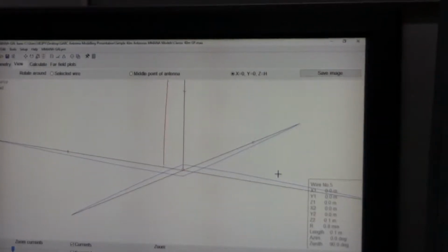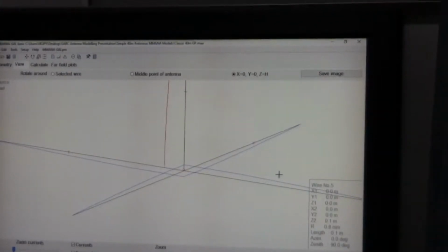Now that's the polarity of the current. What it's telling us is that the current is equal and in opposite directions in the two radials. Same with the other pair of radials, equal and opposite. So at any far enough distance from this antenna, the net contribution to the radiation is zero. It cancels out. Up close you could measure the electric and magnetic fields of those radials.